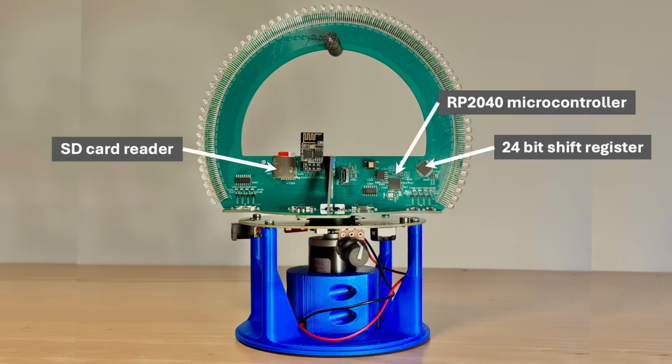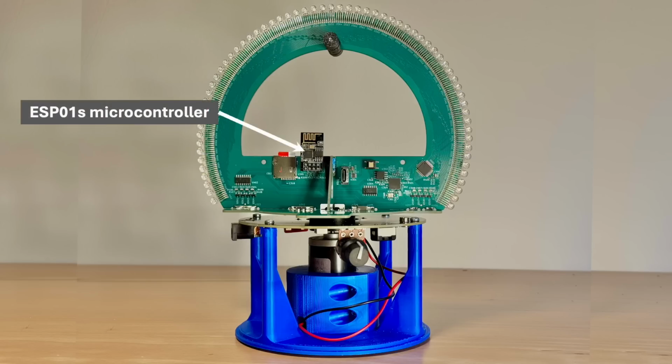On the right-hand side, you can see the RP2040 microcontroller, along with a 24-bit shift register. This register can control 8 LEDs at once. So the microcontroller drives 8 groups of 8 LEDs each, one after another in rapid succession. On the left side, you'll find the SD card that holds the image data. In the center, there is the ESP01S microcontroller. It can be plugged into a socket and is used for remotely controlling the device.